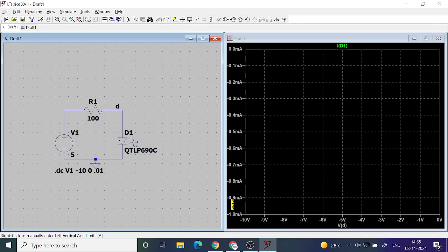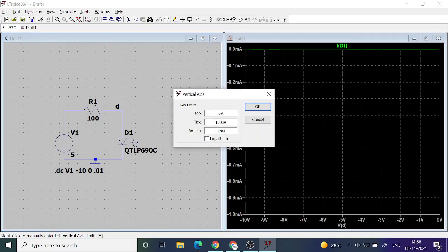Then you can say that it is 0. But for a silicon diode, you plot that in nanoampere, but all others you can put in milliampere. Because for a silicon diode, it is constant and it has a name. We will look at it. It is called reverse saturation current. The value also you need to note down. But here it is not constant actually, and it is very negligible also. Even if I plot this in nanoampere, you will see it is so negligible.